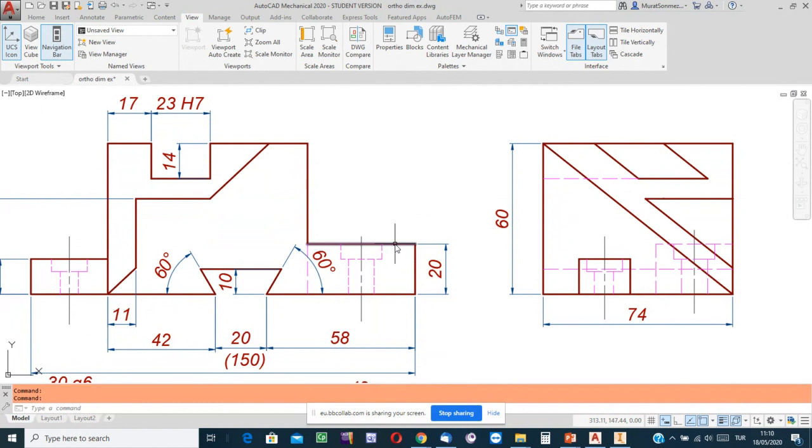Since the cutting tool makes accelerating and decelerating displacements, it will deviate from the correct path, and so the size of the feature at the end of such a deviated cutting process cannot be exact. It will be approximately correct, sufficiently correct, less than the upper limit, greater than the lower limit, or maximum equal to minimum equal.